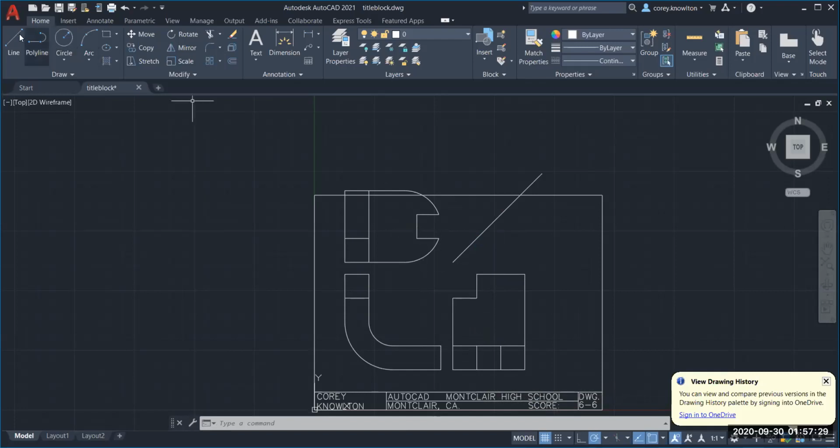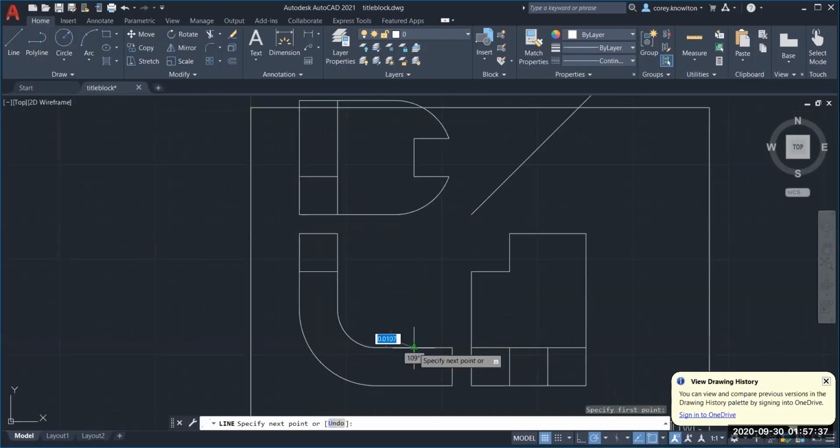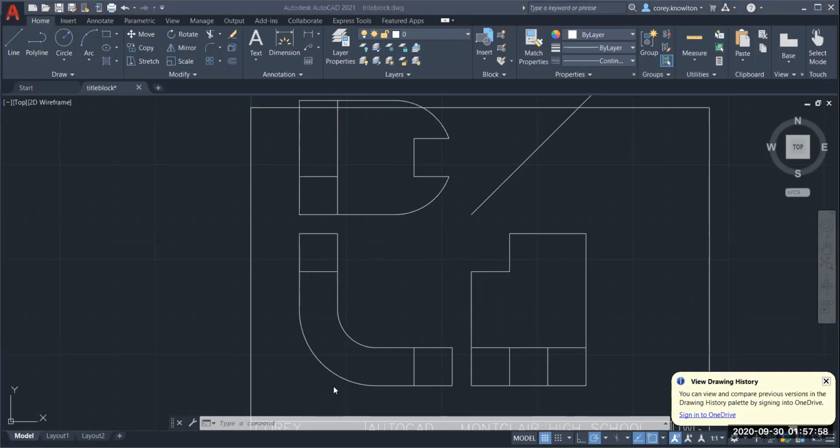Okay, so now I have to draw some hidden lines in here. From here, I want to project the hidden line straight down through here. That's going to be hidden. So this notch is shown here, here, and here. This notch is shown here, here, and here. And the last thing I would need to do is put in my center lines and convert hidden lines here. So let me convert this to a hidden line.